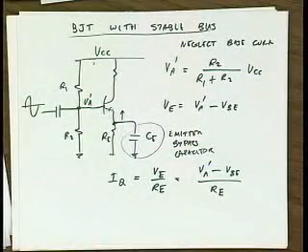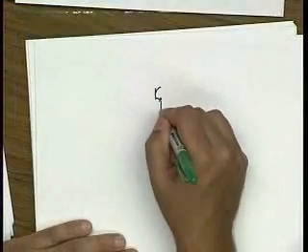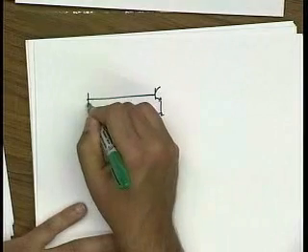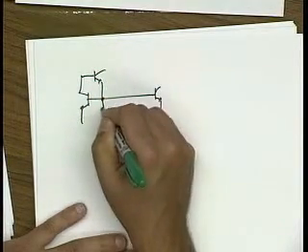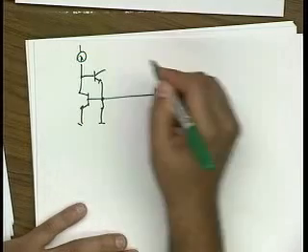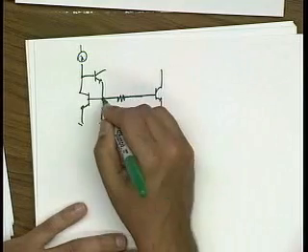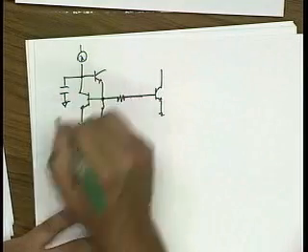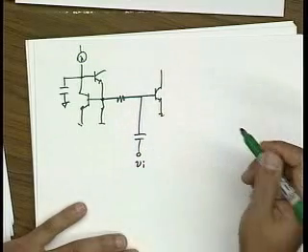Okay. Now this is the old days using discrete transistors. Nowadays, the way we would bias this up would be through a current mirror, right? So let's say this is a current mirror. This is our device. I might use a resistor to isolate this device and use a capacitor here to compensate this feedback loop, and bring in my signal here.